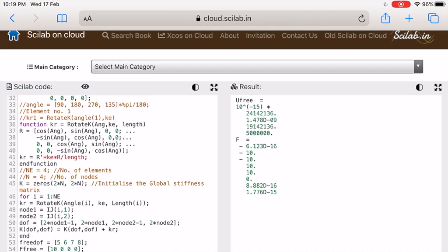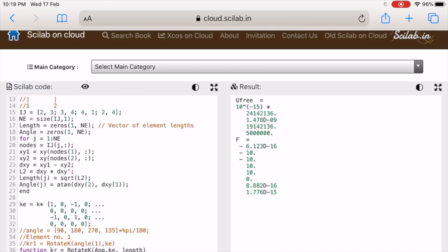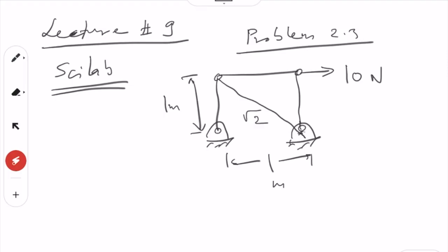Yeah, now we can add the stress as well. So how to do? We have the u, we have the f vectors including the reaction forces here, here, here, here, and we know the displacement. We know how much these are moved up and down, whatever. So value will be 0 here. So if we know the displacement of this up and down like this one, then we can find out what is the strain in these elements, and accordingly we can find out the stress.